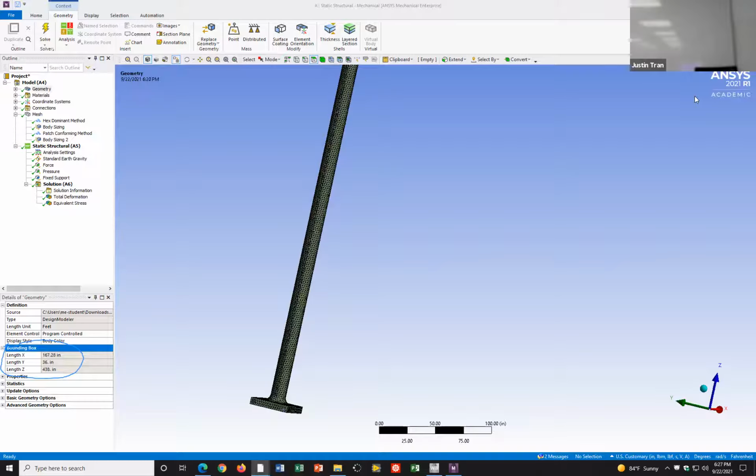Yes. Technically the thinner it is, the better, but sometimes you don't want it too thin. If you have it too thin, it's going to be hard for the computer. If you have something extreme, like 1 times 10 to the minus 16, you start to run up against numerical accuracy. Everything in the computer is done with floating point operations, so if you multiply 1 times 10 to the minus 16 by 10,000, that's a problem. If you make it 1 times 10 to the minus 4, that's going to be a little more accurate. But there's only so far you can go.